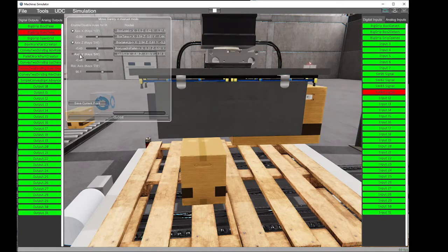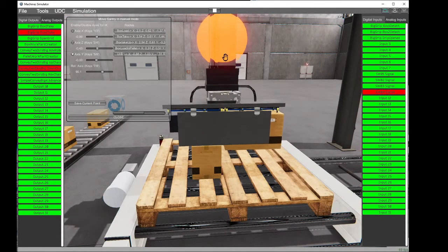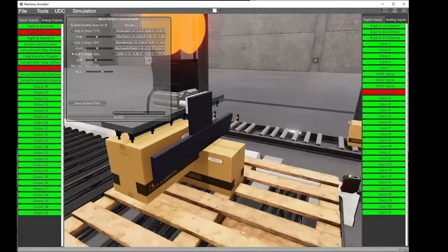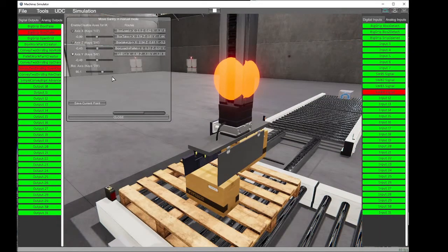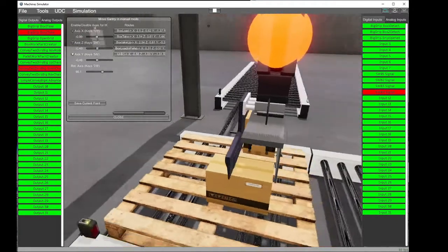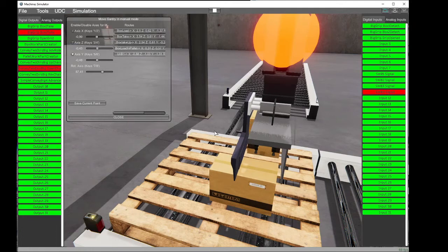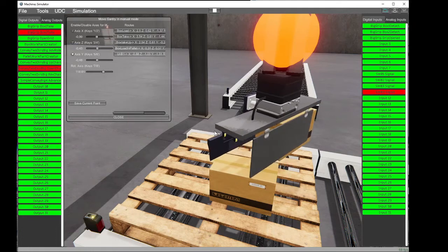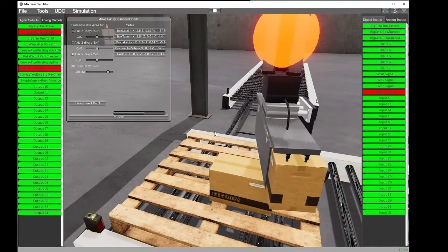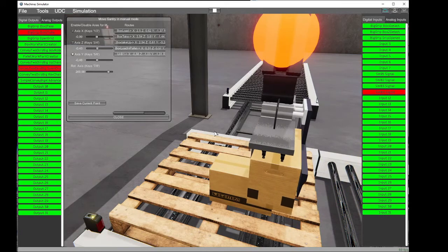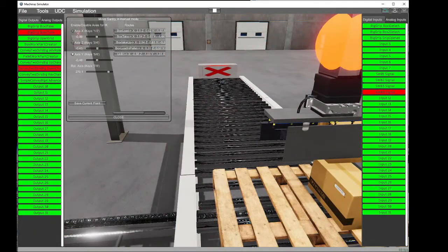Okay. Now I can move the Y axis and here. Oh, no. I made a mistake. In this sense, it will collide. We must rotate in the other sense in order not to collide with the grip. It will be the other sense, so that the plate will be on this side of the boxes. Let's search for the correct value. 2070. Okay. The plate is in this way.